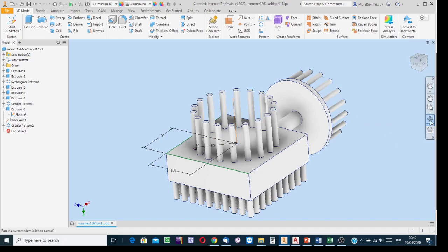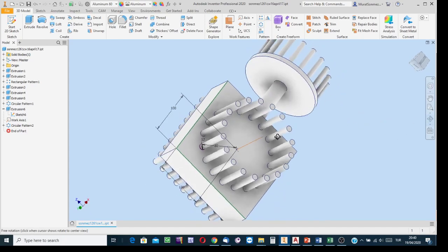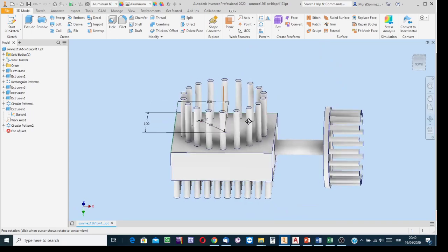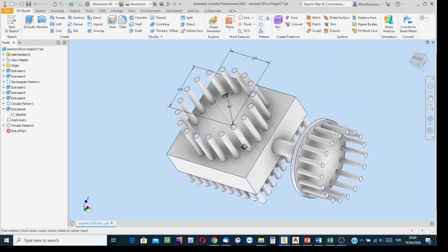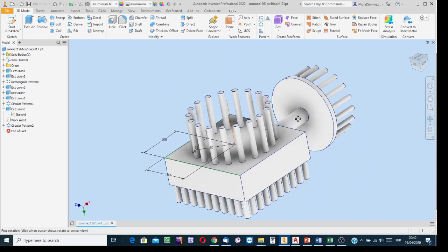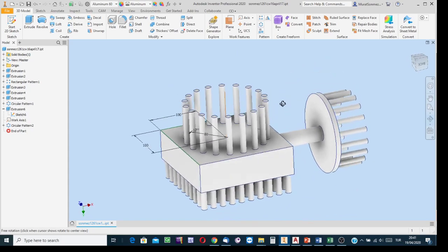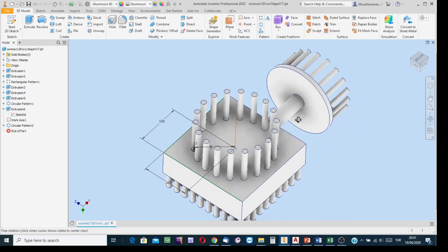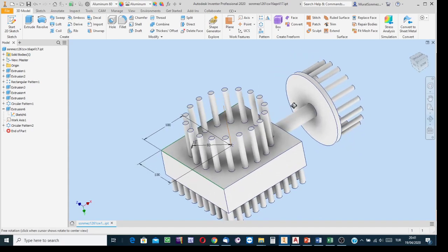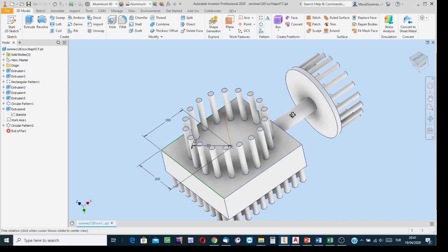That is it. You see, it is a little bit tricky. The trick is the work axis. You should know that since the axis is not defined for the rectangular prism, for creating the polar array, a work axis is needed.